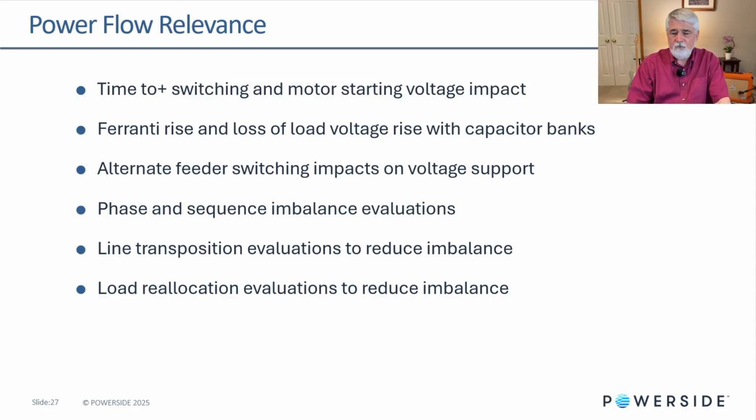Ferranti rise and loss of load voltage rise with capacitor banks. If you have a feeder and it's lightly loaded and you didn't think it through and you didn't run a power flow case, you may have a condition where the voltage escalates to 115, 117% by the time you get to the end of the line.